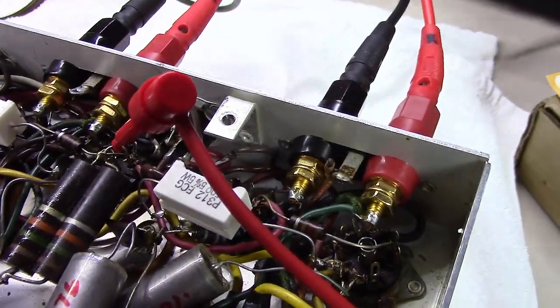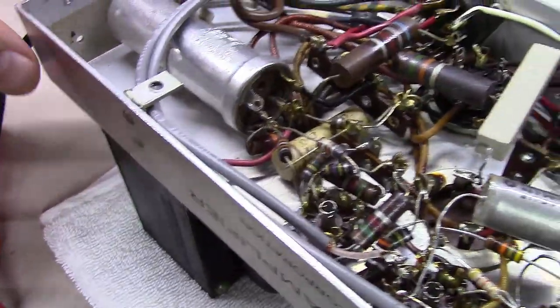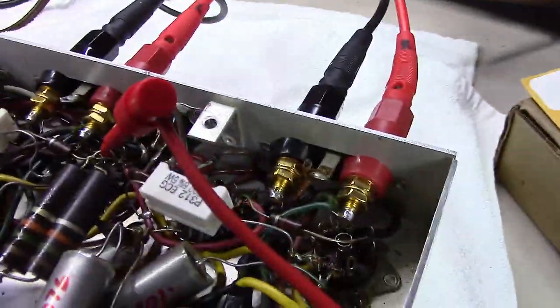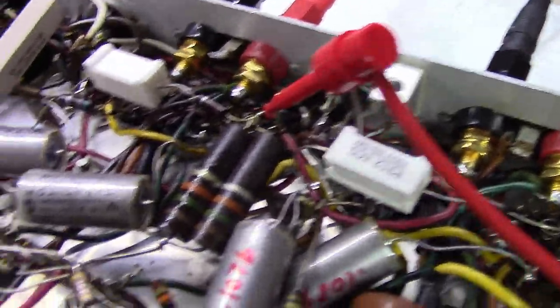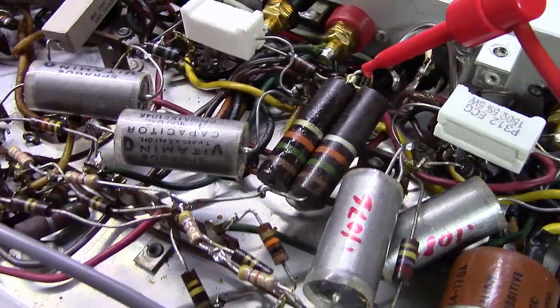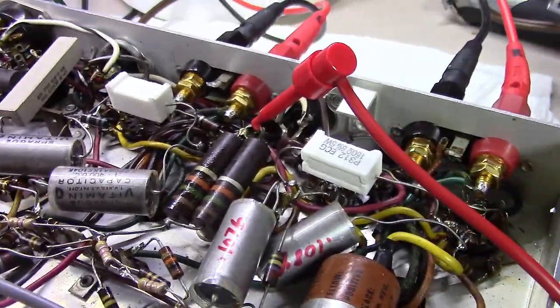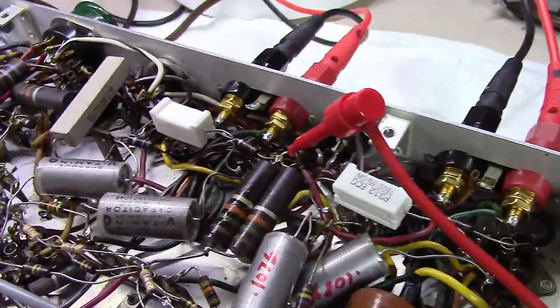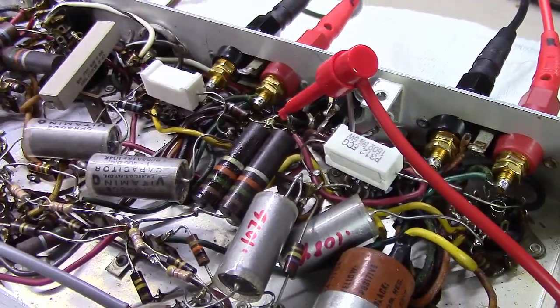So if your right hand happened to touch that and your left hand was holding the chassis here, then those 353 volts would flow through your right arm, straight across your chest, through your heart, and out the left arm and back through this, and it's surely enough to kill you. You just don't want to create a return path through your body to ground per se.